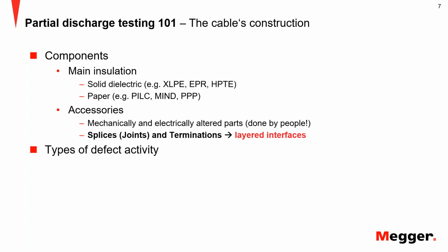And then in general, you have two types of activity when it comes to a defect. When we talk about activity here, I mean specifically the ignition behavior. So first you have anything that can be remotely described as a void or inclusion or something like that, so a concentrated defect in the material itself.